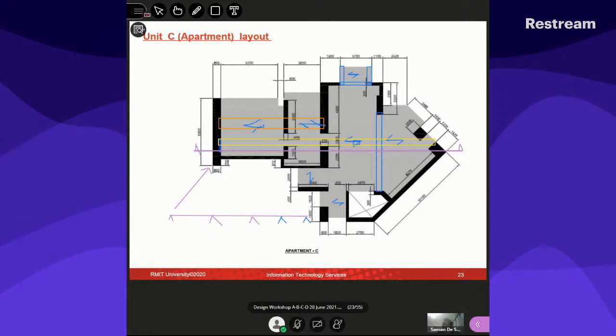And then, of course, if you can do these 2 beams within the same depth as the slabs, that would be fine. So in that situation, inside the same slab depth, you will be having extra reinforcements there. That is another way to do it. So you will be having reinforcements in top and bottom within the slab depth.